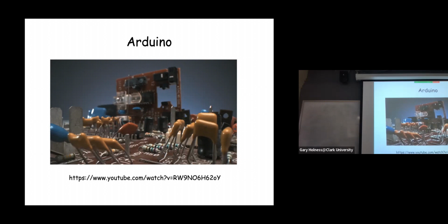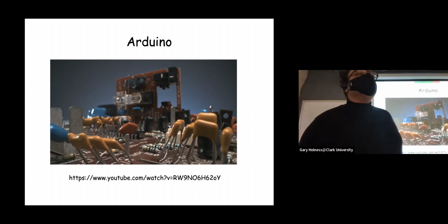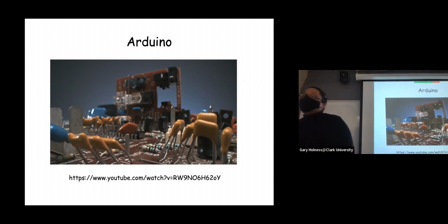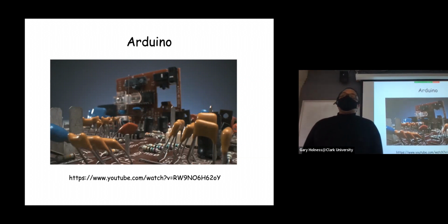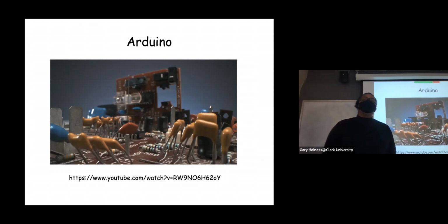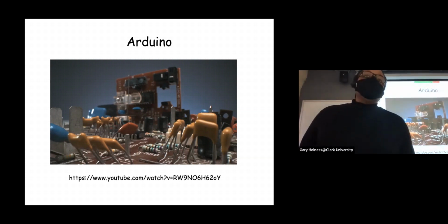But if you had something that was intended for a ruggedized environment, maybe something that was airborne, high enough in the atmosphere that it was subjected to maybe a lot of vibrations because of air currents and turbulence, as well as extreme temperatures, you might want to use the through-hole technology because it's more mechanically durable. Okay. All right. Any questions?